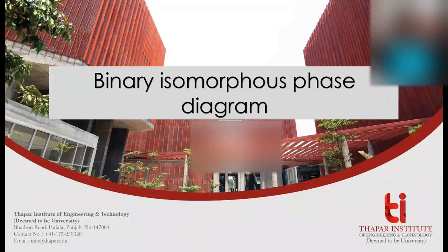So today in this lecture, we are going to discuss binary isomorphous phase diagrams. I already introduced one phase diagram in my yesterday's topic, where we discussed Gibbs phase rule, that is degree of freedom F is equal to C minus P plus 2. That is the case if you are dealing with a unary phase diagram. If you have a binary phase diagram, in that case, we consider pressure to be constant. So in that case, the phase rule becomes F is equal to C minus P plus 1.